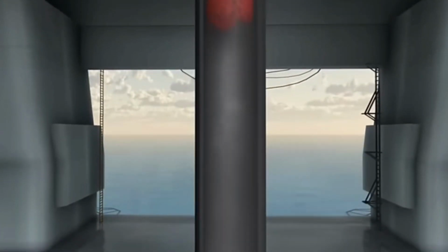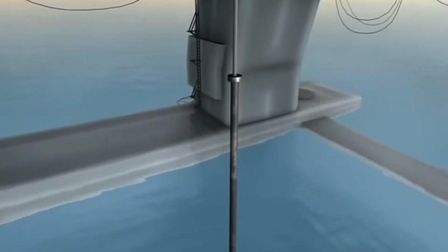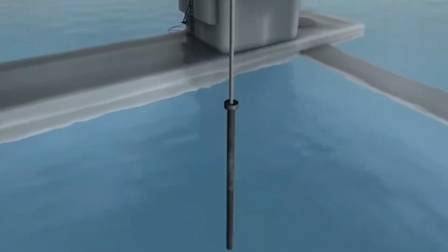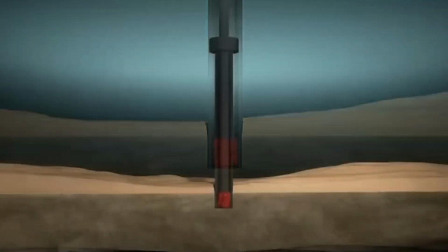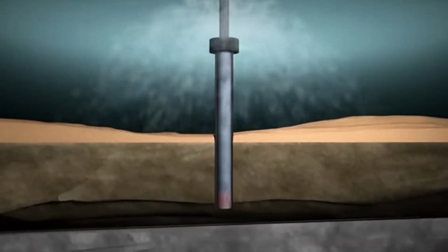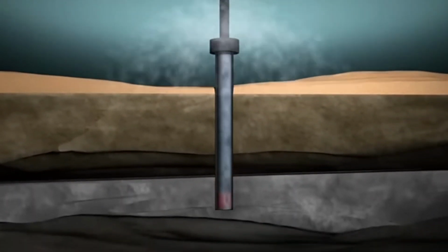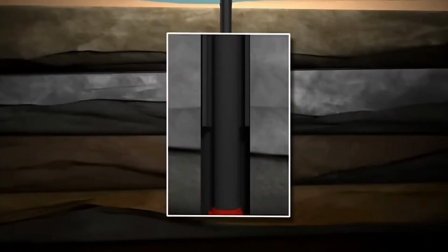The base pipe is assembled at the rig floor, and a drill bit connected to a drill pipe is run through the inside to the bottom of the casing. The entire assembly is lowered to the seafloor by the rig hoist. At the seafloor, the driller spuds the assembly into the seafloor sediments, then turns on the pump. Water or a drill fluid is used to jet the pipe into place until the wellhead is just above the seafloor. With the base pipe and wellhead at the right depth, the driller will release the bit and drill string from the jet pipe and drill ahead.